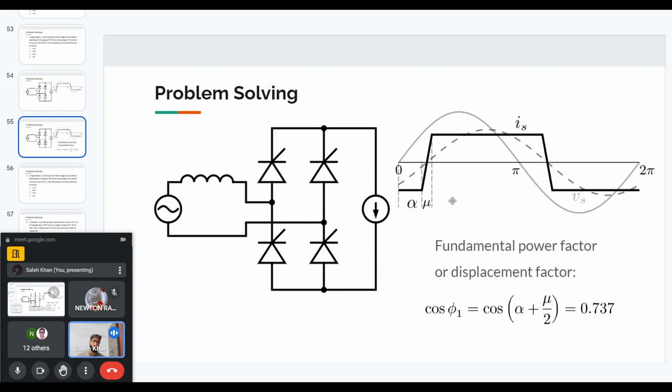However, there will be one advantage: the THD will improve. If you see the multi-phase, the multi-pulse converter in the lectures, you will see that the THD will improve, because with an inductance at the load, the change in the current will be gradual.